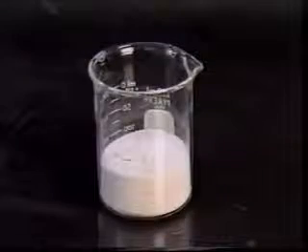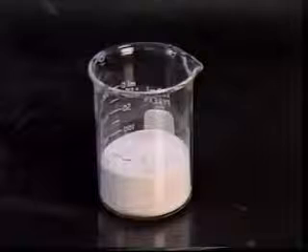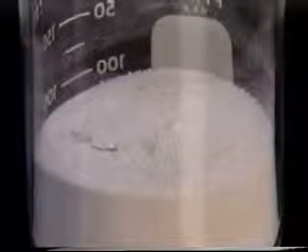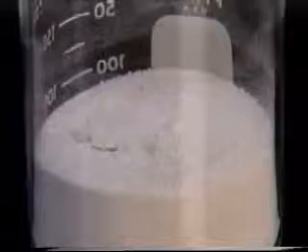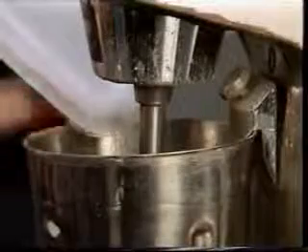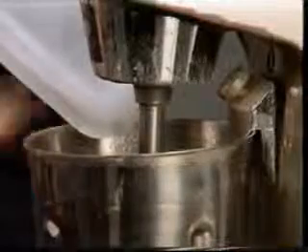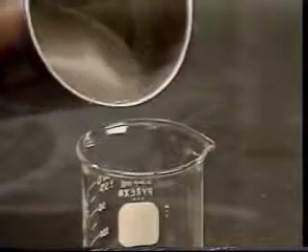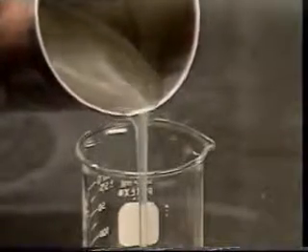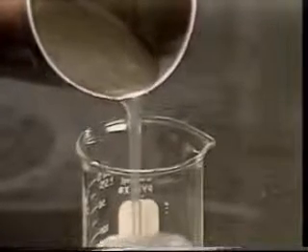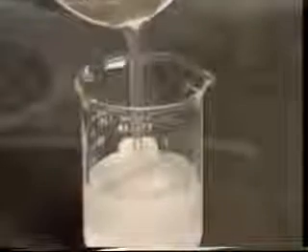Another class of additive used to increase viscosity is polymers. These may be natural, organic compounds such as starches, gums, or cellulose derivatives, or they may be synthetic polymers derived from petrochemicals. These compounds are used for a variety of reasons besides viscosity control. The high molecular weight and highly branched high viscosity structure of the polymer compounds are what cause the increase in viscosity and gelation characteristics when they are added to a mud.